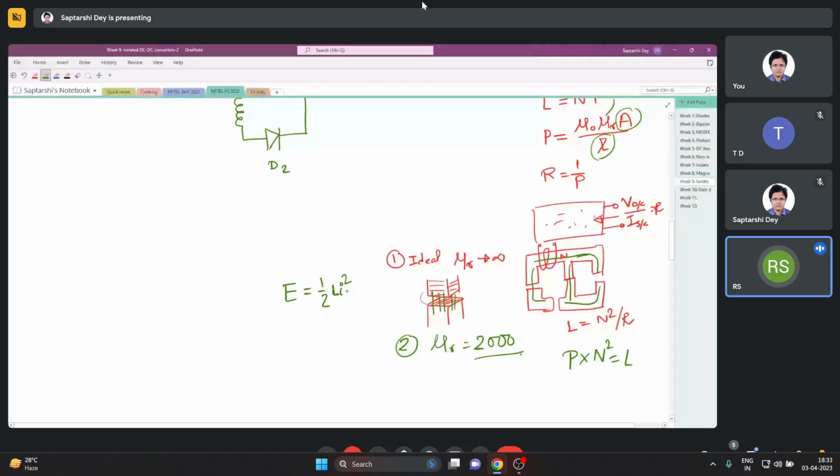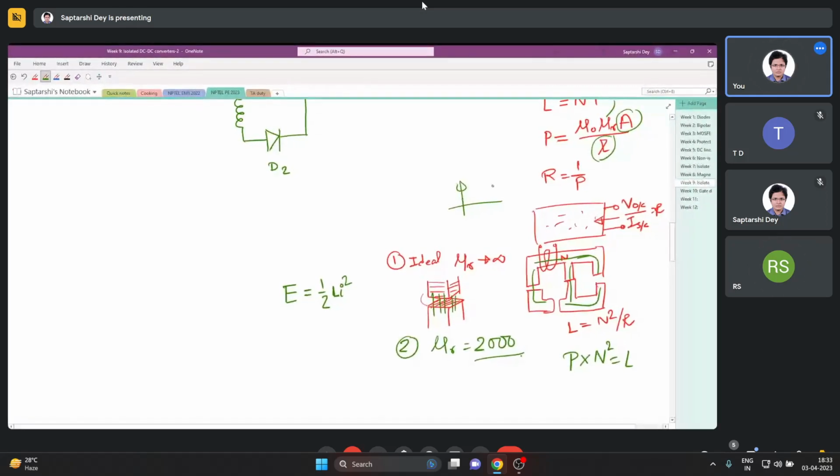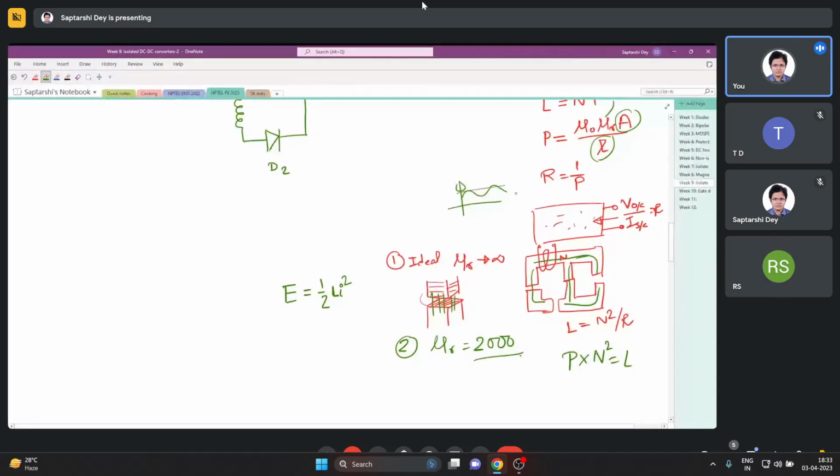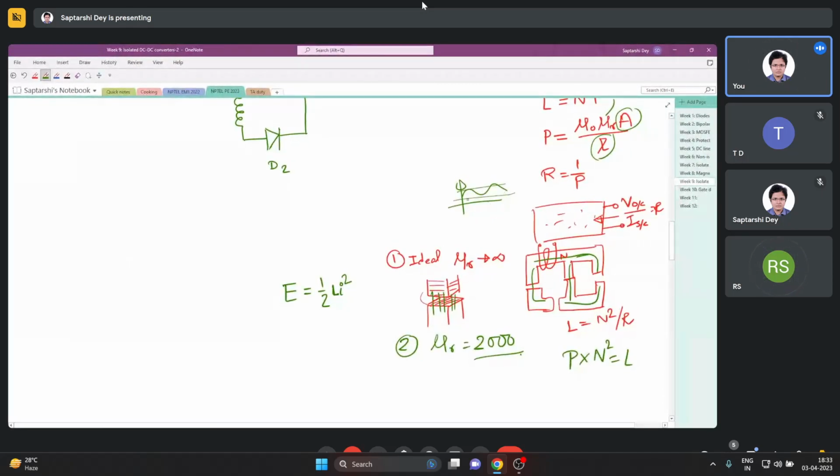No, while discharging, sir. Oh, okay. If you have a capacitor, that will increase the voltage of the capacitor. So there will be a ripple in the capacitor voltage. Now, depending on how much ripple you desire, that will give you the value of the capacitor. That is how we will calculate the required value of capacitor that you need there.